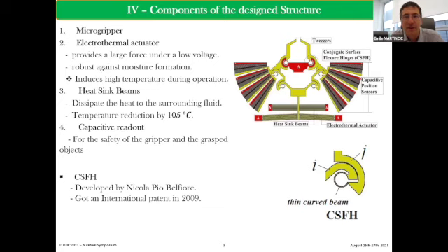Another question, but I suppose it's a more difficult question because you are not running into fabrication. You said that you have a thickness of 25 microns. So I suppose you'll be using SOI wafers if you target silicon, and then 25 microns thick to etch with a 2 micron gap is quite demanding. I have it in mind, but I think it's a little bit risky. It's a very ambitious device.